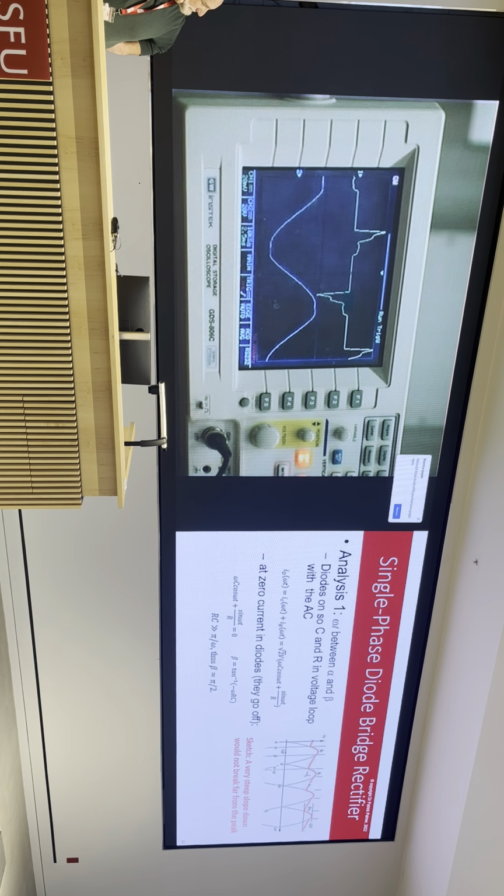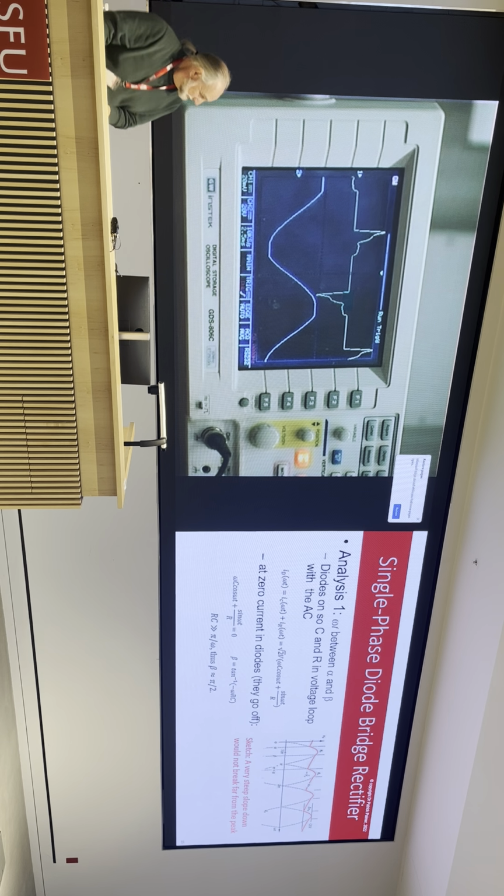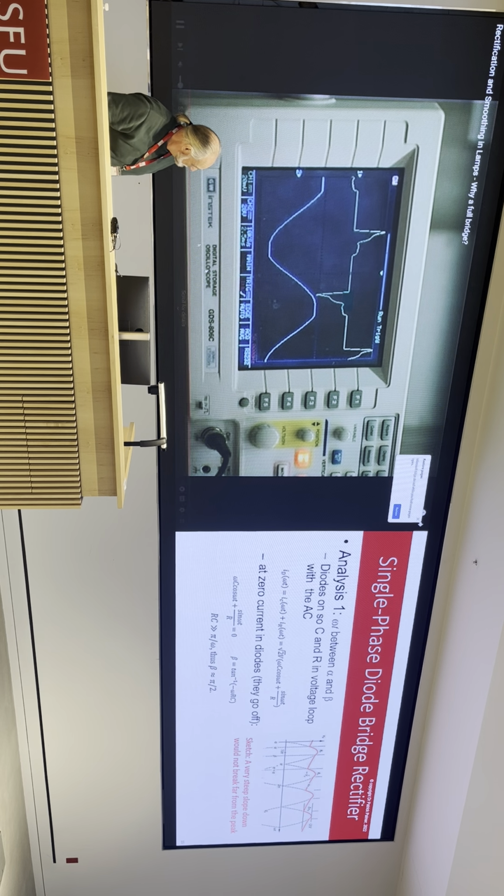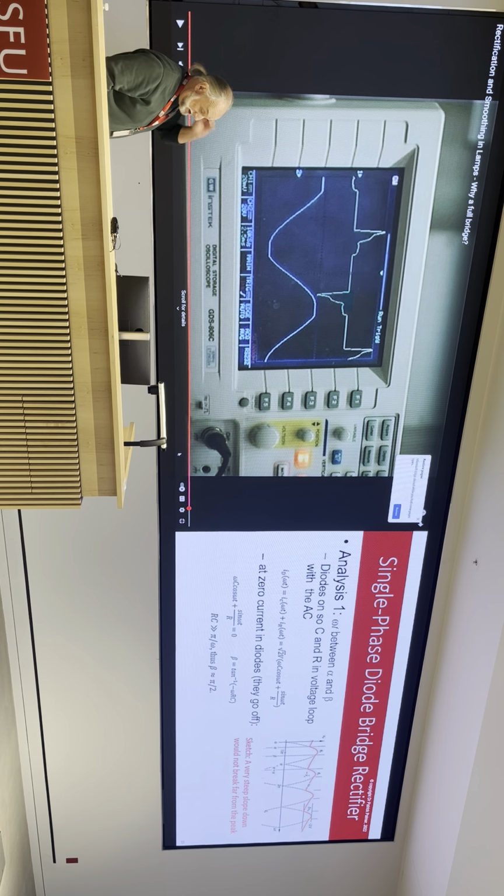And there we can see that the mains voltage is rather flat topped during the charging period, but it coincides with taking current out of the peak of the supply on both sides, and therefore it has upset the mains voltage a little bit, simply because of the impedance of the supply, and that's the mains voltage coming into this bit. So actually, if you look at that closely, you see the flat top actually doesn't quite coincide with that spike.